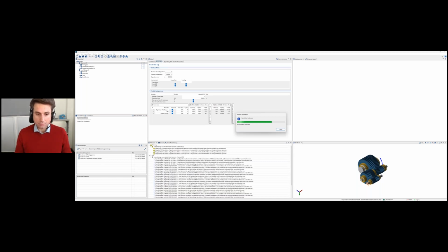So within the model snapshots, you will see the pressure on the flank. You can access the service life for your bearings and the shaft safety factors. And in addition to the simulation of all 3 load stages, we get a 4th model snapshot containing all accumulated values.